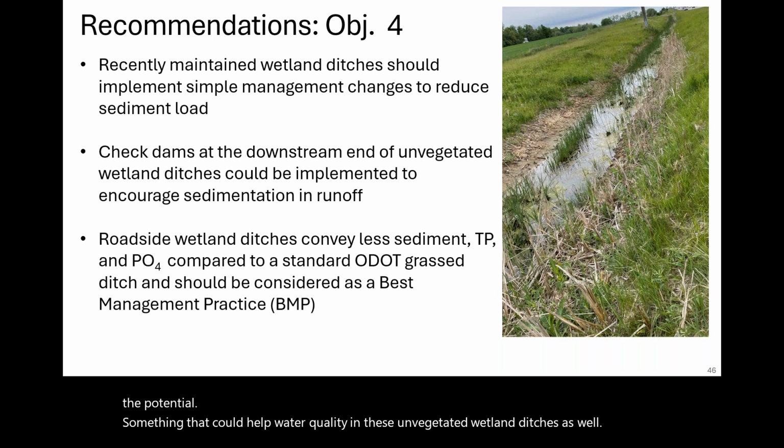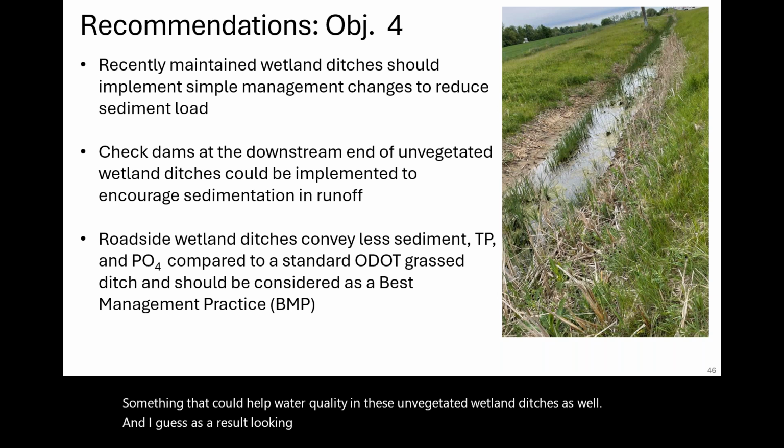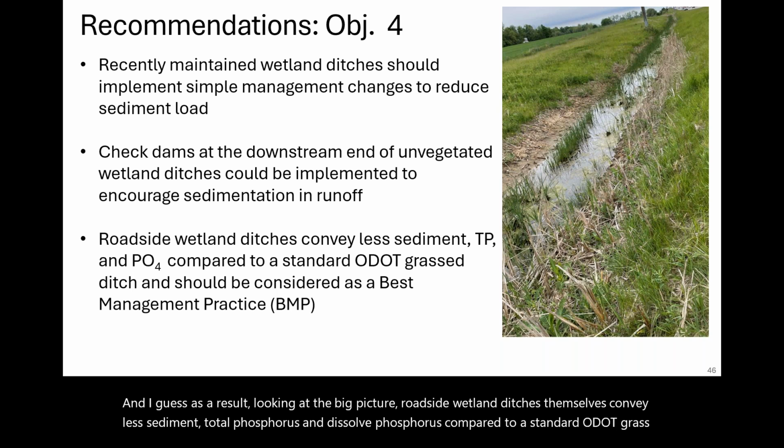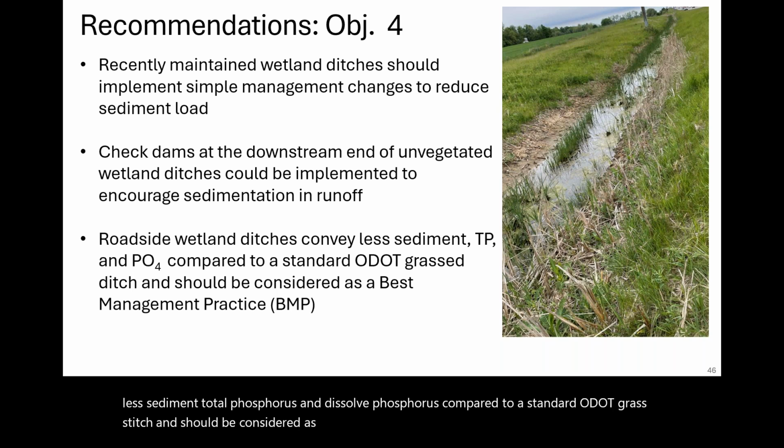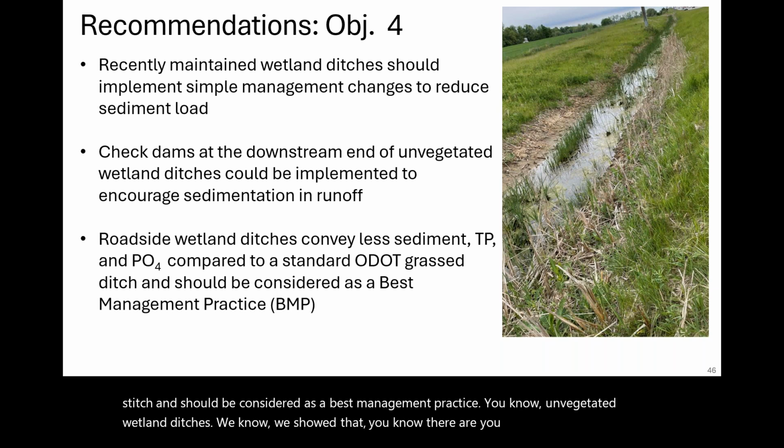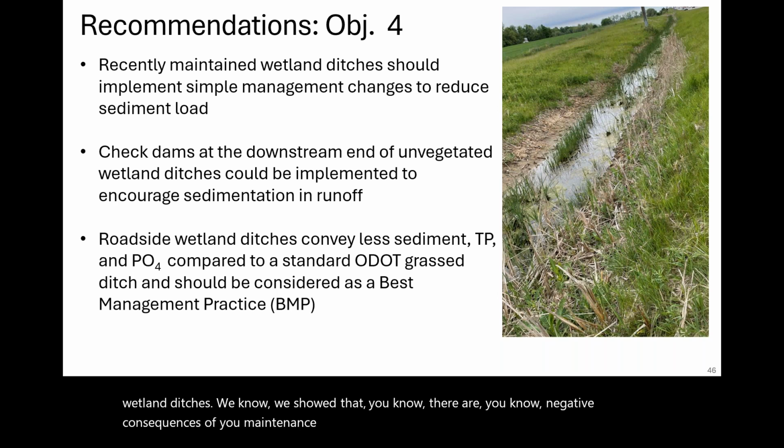And as a result, looking at the big picture, roadside wetland ditches themselves convey less sediment, total phosphorus, and dissolved phosphorus compared to a standard ODOT grass ditch, and should be considered as a best management practice. Unvegetated wetland ditches, we showed that there are negative consequences of maintenance on these wetland ditches.